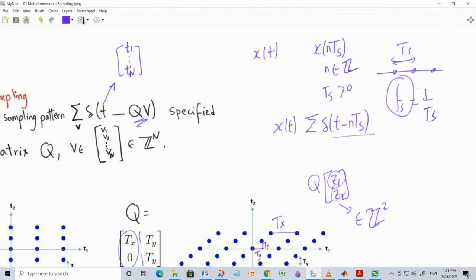And so it means that you have more storage requirements. You are basically burdening your digital signal processor because you will have to deal with a larger number of samples per second. Okay, so increasing Fs is sort of good in terms of getting a signal that is as close as you wish to the original continuous time signal. But again, think about this big problem, which is an increased number of samples per unit time means, again, this will put a burden on your transmission.